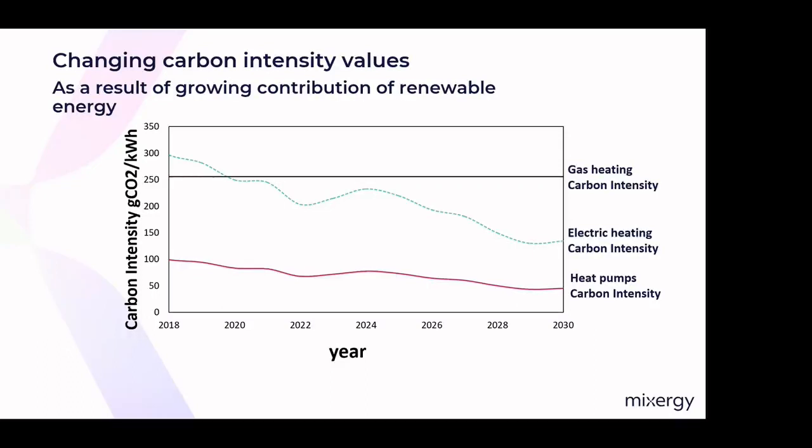This has been recognised within our building regulations, for example with heat pumps, because if we get a COP of 3 from a heat pump, we can then reduce the carbon intensity by a third, and as a result it allows us to use technology which is a lower carbon intensity than gas, which is fixed at 250 grams of CO2 per kilowatt hour. We are now seeing a rise in assets that utilise electricity as the carbon intensity is falling and it's becoming a better solution for our planet. But it makes balancing the grid more important.